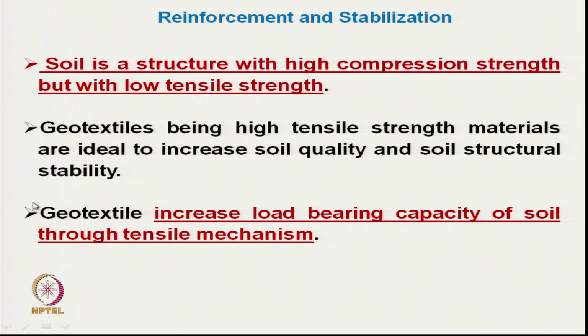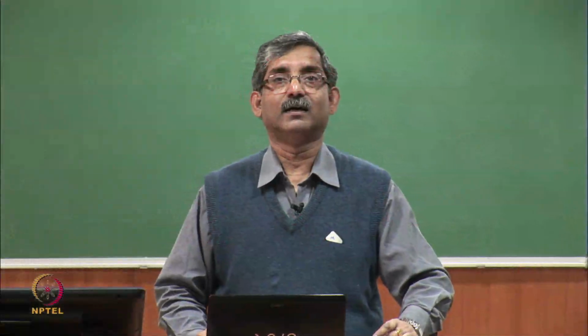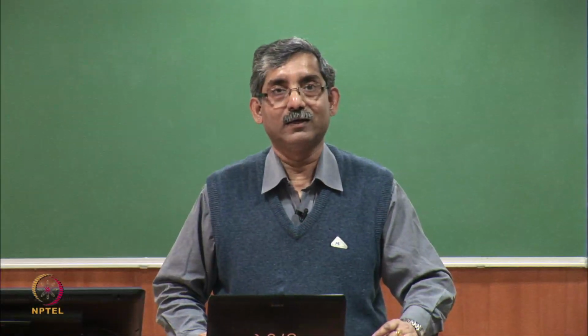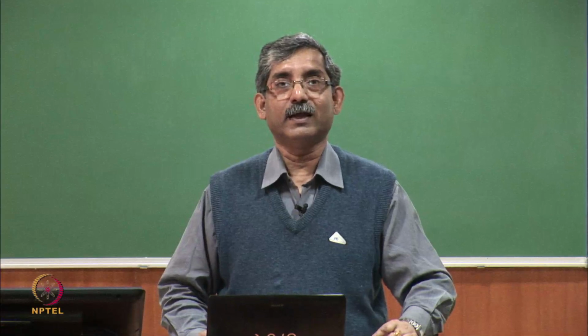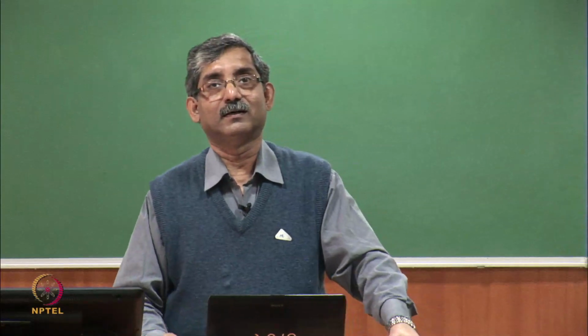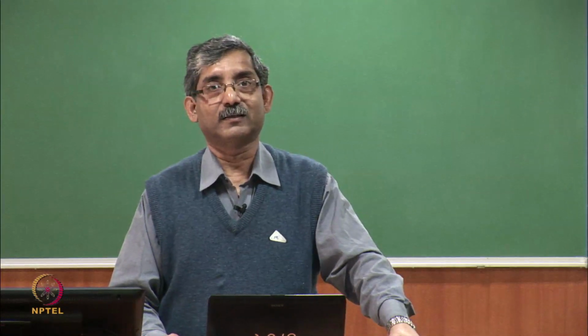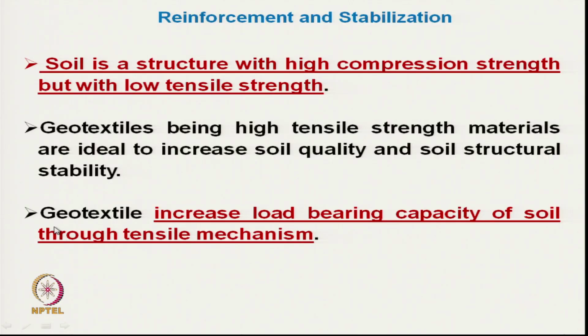Once geotextile is put inside the soil, it enhances the tensile strength. So, geotextile increases the load bearing capacity of soil through a tensile mechanism.